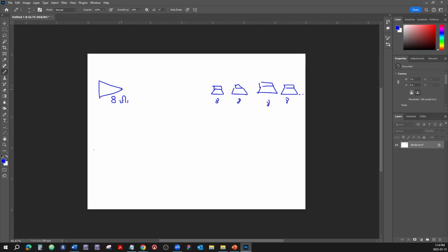Now, if we connect them in series, then we're going to have a huge total impedance for those. We're going to have 8 ohms here, and over there we could have 500 ohms. No good. No maximum power transfer. Let's see what happens if we connect them in parallel. Then, out of 50 speakers, we're going to have pretty much close to zero, because when we keep adding in parallel, we are providing one more pathway for the current to flow, so the total resistance goes down. And it's always going to be less than the resistance of the smallest device. So that's also no good. We're definitely going to burn out the amplifier. It's almost like connecting it straight to ground.